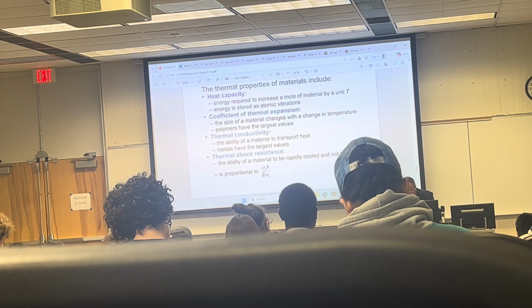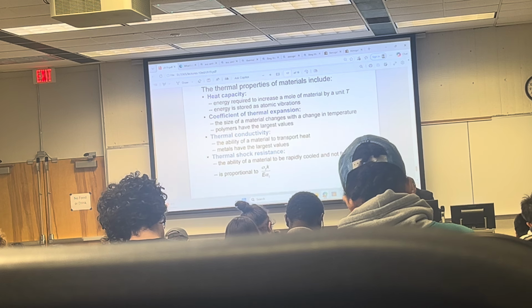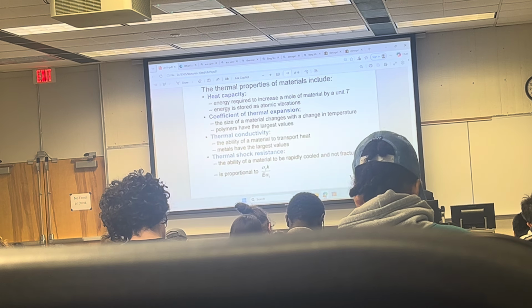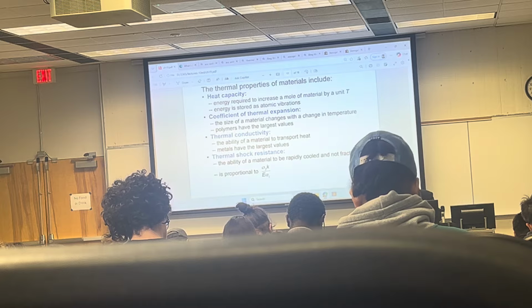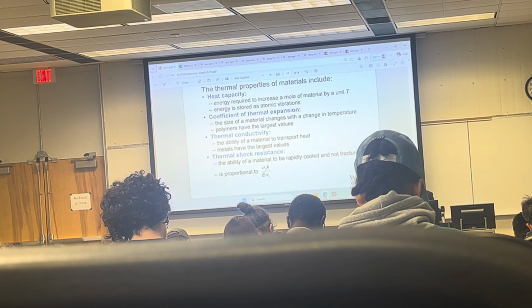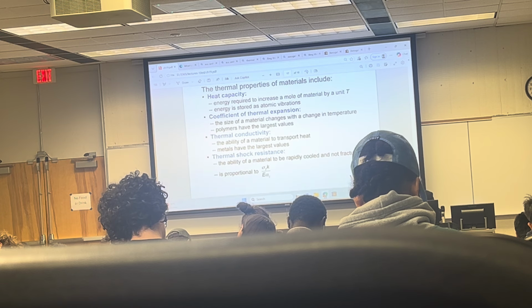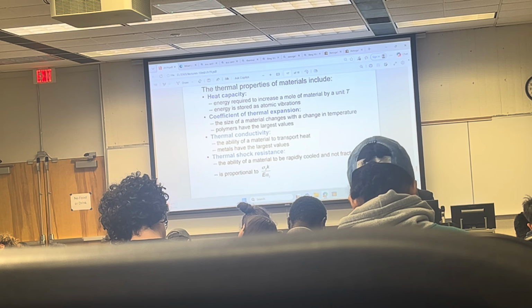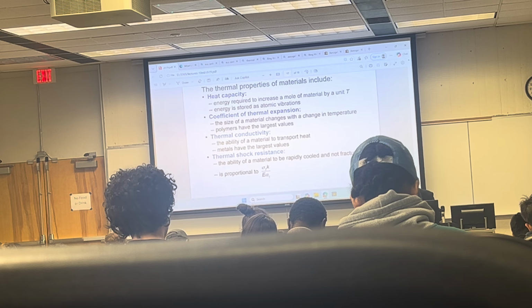Another question is about chapter 10. There's homogeneous nucleation of a metal. You're given the latent heat of fusion and the surface free energy, and you're given the melting temperature. The first question is asking to calculate the critical radius for the supercooling, and it gives you the temperature.